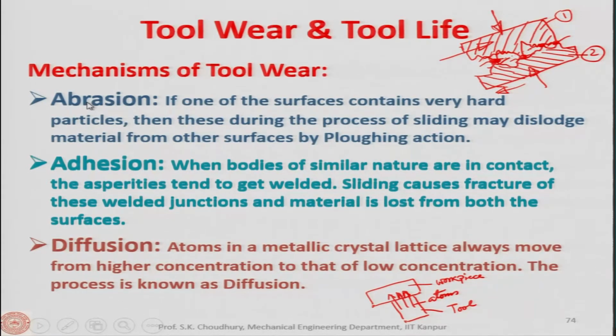Normally, abrasion and adhesion may happen together or separately, but diffusion is something else, because diffusion happens at a higher temperature. During machining the temperature goes up, but more so for high speed machining.